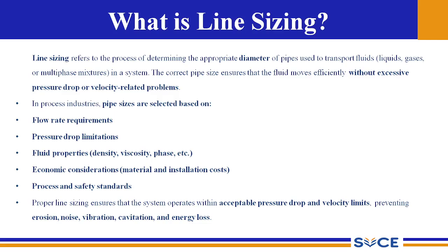First is, what is our flow requirement? Whether the pipeline can withstand the required flow rate, and what are the pressure drop limitations that need to be satisfied. Then the phase of the fluid, whether it is a gas or a liquid, whether it is highly viscous or less viscous, high dense material or low dense material, along with the corrosive characteristics, and the compressible or incompressible nature of the flow. All these come under the fluid properties which need to be considered while doing the line sizing.